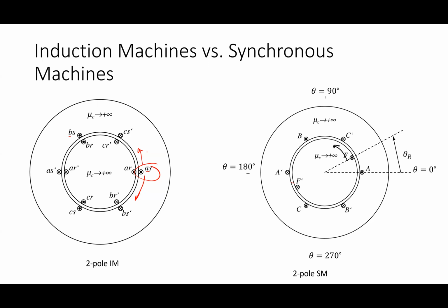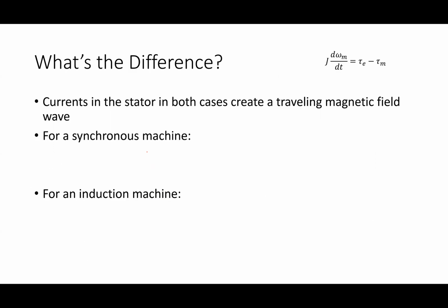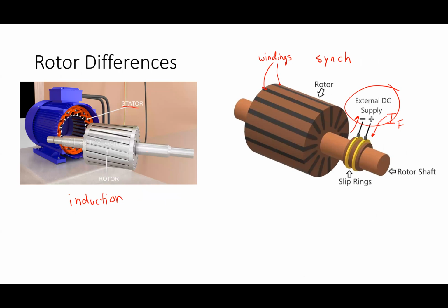Now, in reality, from a practical perspective, that's really hard to do. What you see is like when I brought that winding belt in before. What you have is windings that are held up in slots. And so you distribute them in such a way with those winding belts that they sort of look sinusoidal, and you see something like this. You look at that picture there, you can see there's windings hanging in slots in the iron. So there has to be slots to kind of hold them in place, or else they'd fall.